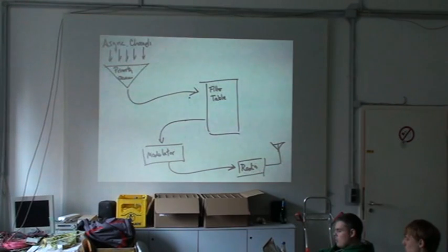And then we don't have to transmit anything else. The layer 2 code in OpenBTS just goes to sleep. It sends enough idle frames to fill the table and it goes to sleep. Because we know that down in the modulator it is going to keep playing that same pattern over and over and over from the filler table until we change it.